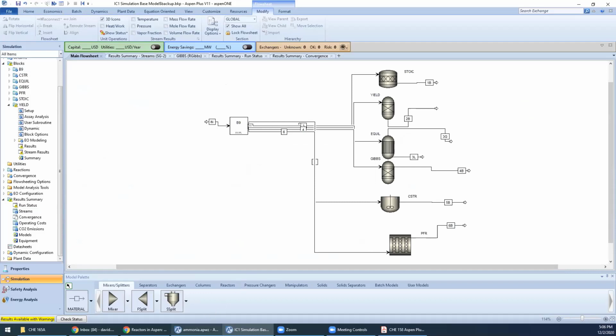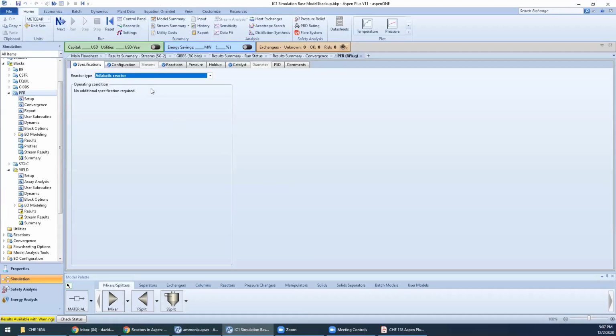So really quick, to see how complicated, or any questions on this before we see how complicated it can get? So I guess, do you advise just running all of them just to see which ones will give us reasonable results first? If you have a set of reactions, yeah, it does not hurt to run the Stoich, because what you'll do is you'll pick a rigorous reactor like a PFR, okay, adiabatic, or maybe a reactor with a specified temperature.